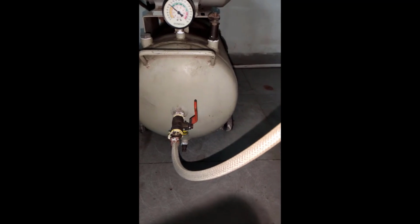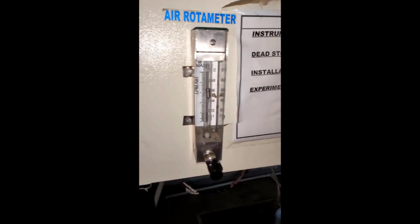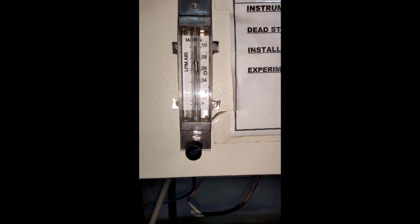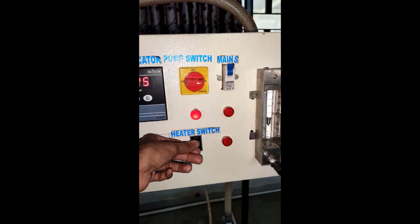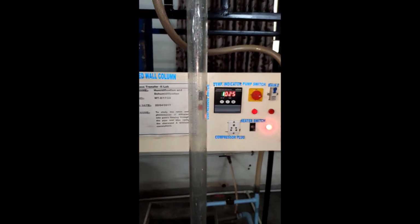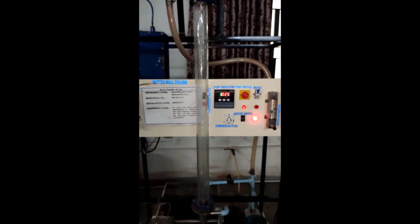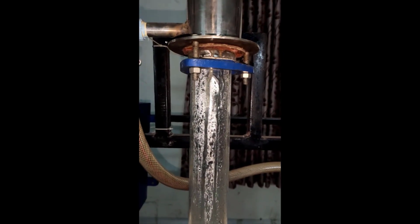Okay, so before the inlet to the column, you can see here that the thermocouple is installed, so that we can have an idea of the temperature, or you can say wet bulb and dry bulb temperatures. So this is the air rotameter through which we can adjust the flow of the air. Okay, right now it is already adjusted. Okay, now after this we have started the heater switch, so that now the air will be heated, and from the bottom of this column the air will flow through the central portion. Okay, so this is how the water will flow.